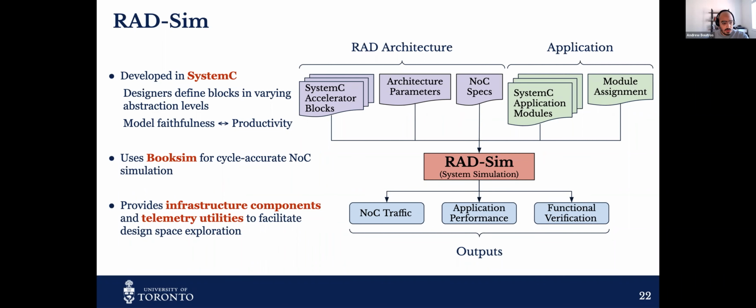Behind the scenes, RAD-Sim uses Booksim to do a cycle-accurate NoC simulation. So we don't have a NoC model, we actually simulate the NoC transactions. And Booksim is the go-to simulator for studying NoCs. And besides that, RAD-Sim provides infrastructure components and telemetry utilities that help you probe into the implementation of your application on a RAD, identify bottlenecks, and facilitate your exploration of the design space.